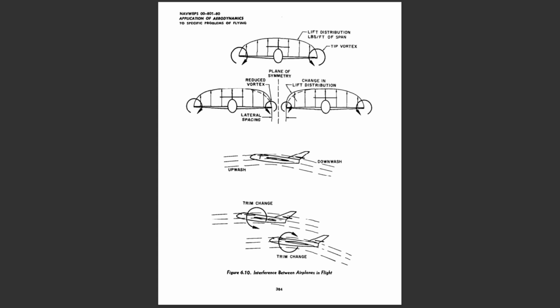During in-flight refueling, essentially the same problems of interference exist. As the receiver approaches the tanker from behind and below, the receiver will encounter the downwash from the tanker and require a slight, gradual increase in power and pitch attitude to continue approach to the receiving position. While the receiver may not be visible to the pilot of the tanker, he will anticipate the receiver coming into position by the slight reduction in power required and nose-down change in pitching moment.